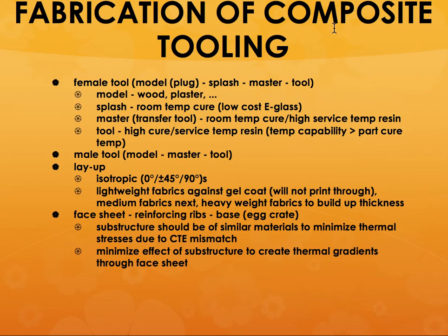So the fabrication of composite tooling, the different steps are listed here. I'm not going to go too much into detail about that. Basically, you are going to lay up the composite. You have a face sheet that is slightly different, and the bottom could be what is called an egg crate type of design, so that you reduce the weight even further. So, for example,